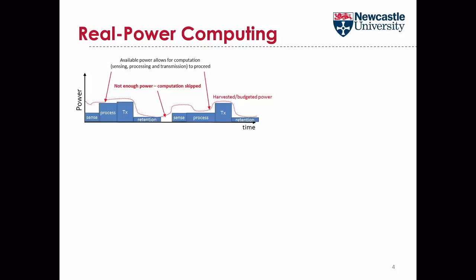So how do we, for example, handle a system where there is no option for energy storage at all? It could happen in energy scavengers, for example. You don't have any energy storage option at all, so you have to live with this kind of transparency from the high-level side. That would mean that you have to do a lot of offline characterization, understanding how the energy supply works, and also understanding the variations over time, and making sure that the developers and also the ecosystem of devices that you have always know how to deliver on the computation based on the power budget.